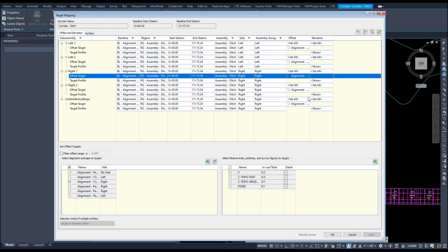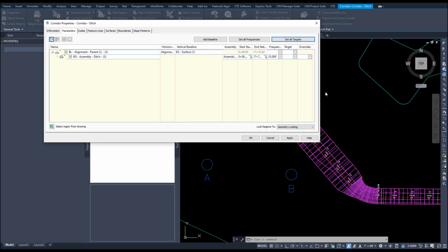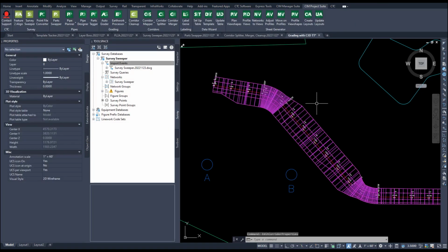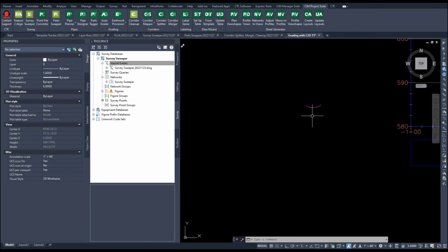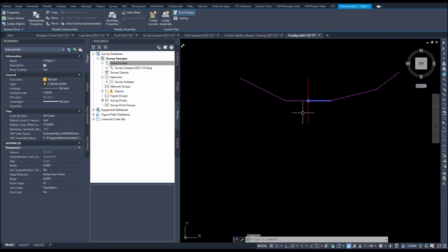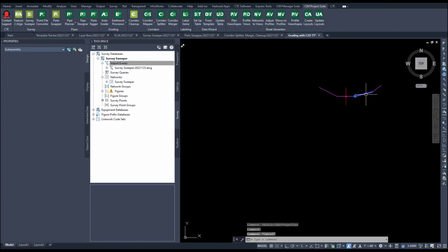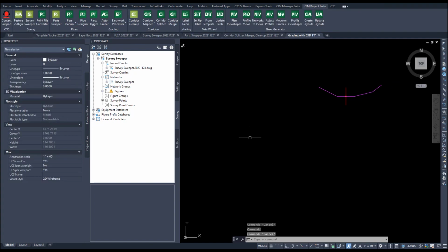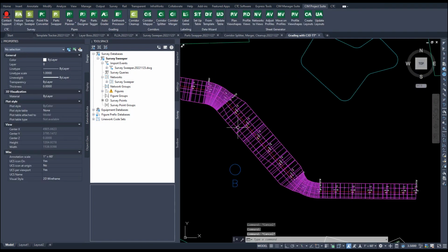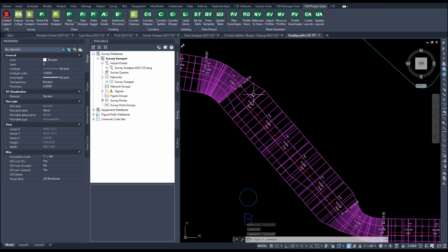Now I have to set them all manually, and sometimes we just need a fresh restart on some of those. So if I cancel, instead of setting all those targets one by one, I can use corridor cleanup to get right back to my assembly of how that was drawn. Notice that this is 5 feet wide, and these lengths as well, 10 and so forth. Whereas on here we have this widening. Maybe we need to change and update this real quick.